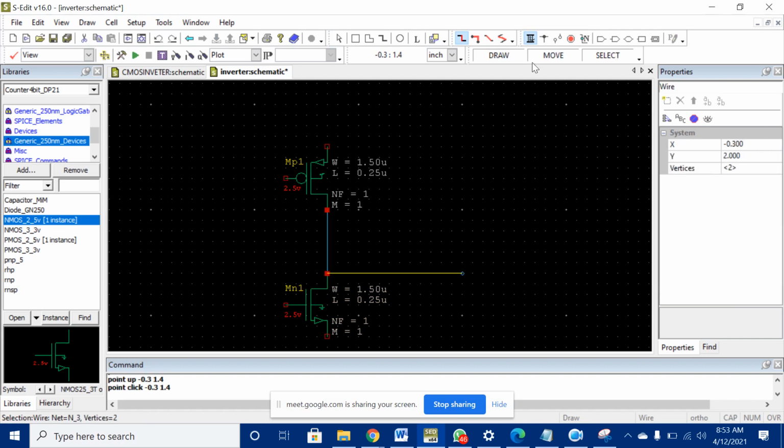So here you can see, this is the wire. Okay, and this is the solder point. Solder point means if I want to merge 2 points, then you can use that. So connection on disconnect, then next net cap, and this is a net label. A net label can be used when the circuit is complex, I will tell you when to use it. Okay, then next this is input, then next this is output port. Okay, and this is the select, so we can select like this.